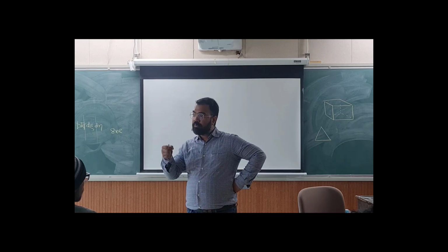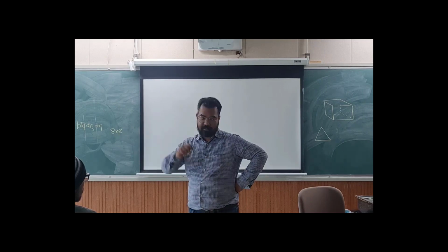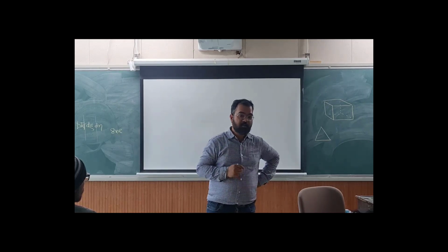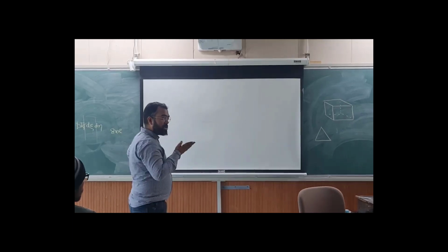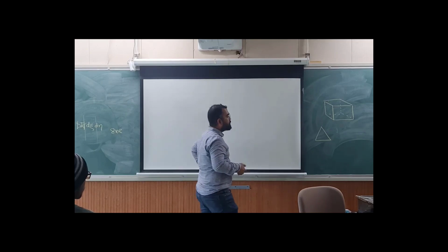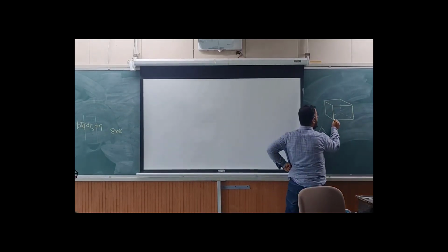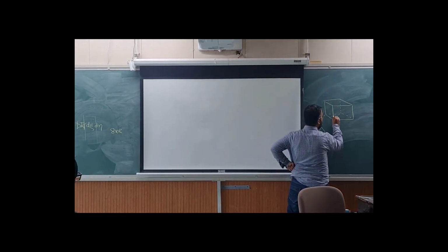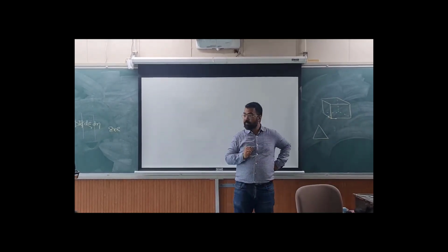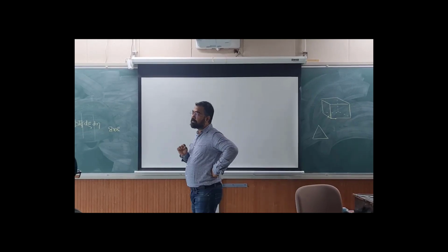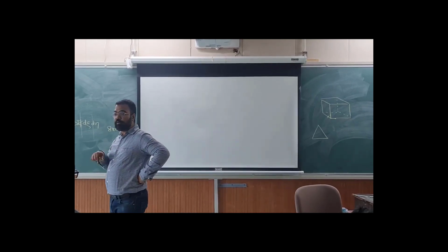So tell me those 3 freedoms. Like U, V, W. So you have U1, V1, W1, U2, V2, W2. So displacement in X, Y and Z direction. Each node in 2 dimensions had 2 degrees, now you have 3 degrees each. So it becomes 24. So for one element, the stiffness matrix will have an order of 24 cross 24.